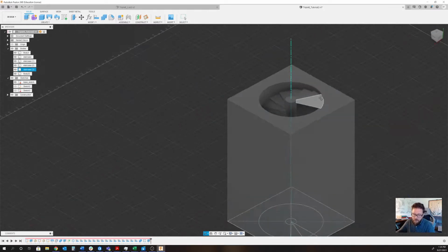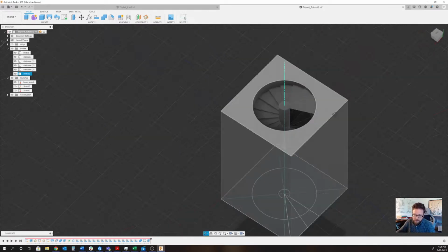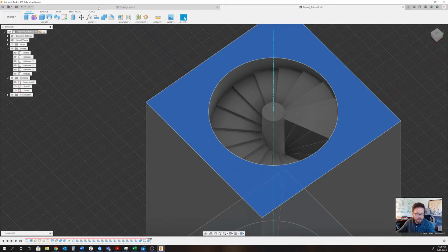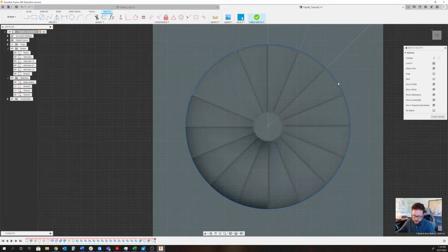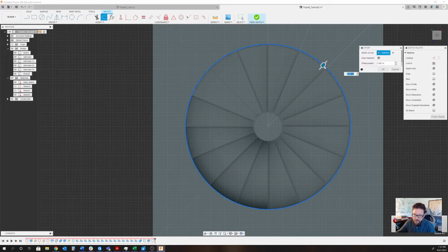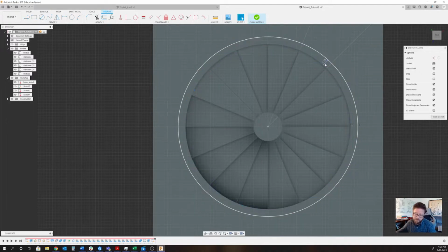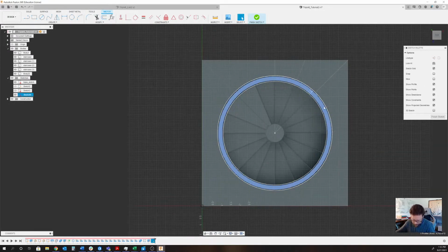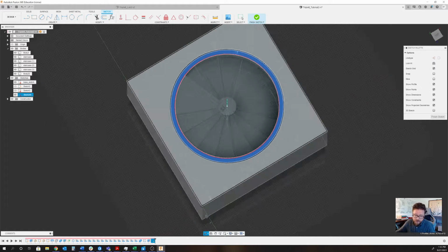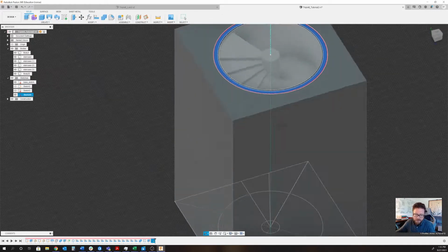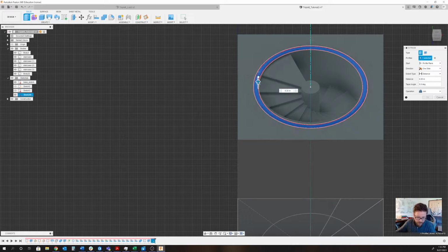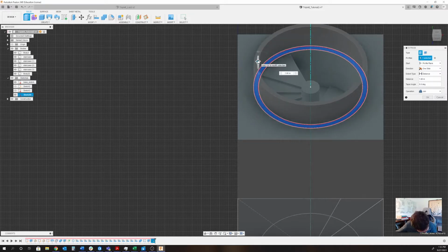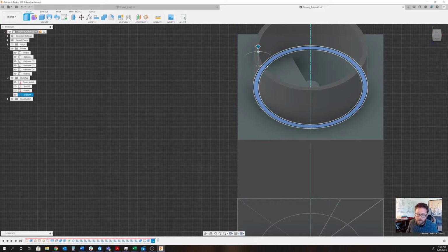Good. All right, so now we want to do some additional walls out here. We're going to do some things on the top of the building that we haven't done on the bottom. So let's just create a new sketch on top of this plane right here. Select the plane first. I'm going to grab this circle and I'm going to just offset it so that I get a nice clean line there. And this is going to be a very thin wall, just 0.25 meters. From there, I think I can just skip this next step. Well, let's do it in the order that it is in the diagram. So now that we have this ring here, I'm going to create another new body. I'm going to extrude this up, and it looks like 3 meters up. Okay, all right, so we have that here.